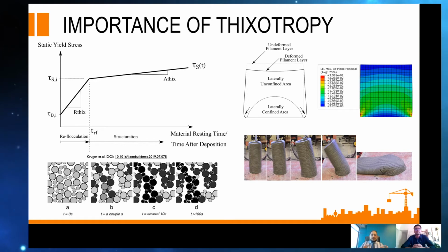Can we then also say that when it comes to 3D concrete printing, the batch that you mix up can only be done in certain quantities at a time? You can't just do a whole couple of cubes one time. You must control the batch that you mix up for a specific print. Absolutely. Theoretically, you could do very large batches, but your quality control would suffer from this. So it would once again be a practical consideration where you trade off the level of surety that you have as to what your material supply is versus creating large quantities, economies of scale in this regard.